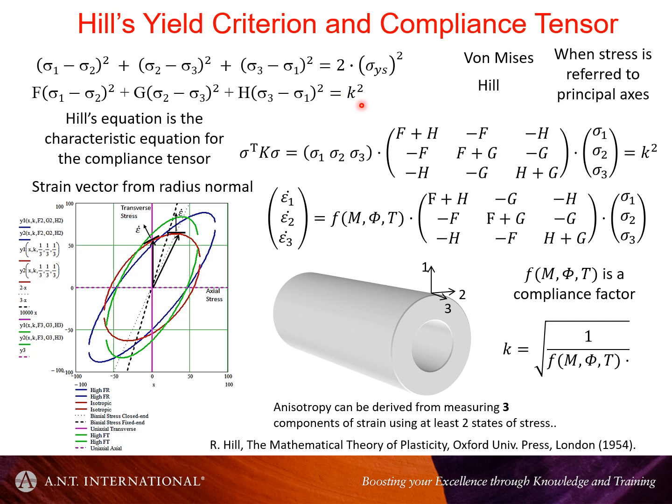But in an anisotropic material, well, actually any material, one should consider this condition to be an energy condition. So at some point, when you increase the stress, you affect the elastic energy in the material, basically from Hooke's law. We change the elastic energy in the system, and when the elastic energy, or the work done in an elastic strain, exceeds a certain value, we get yielding.